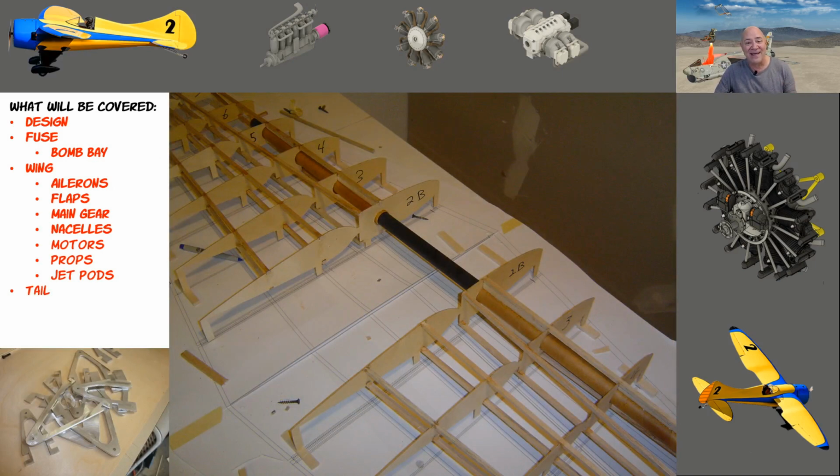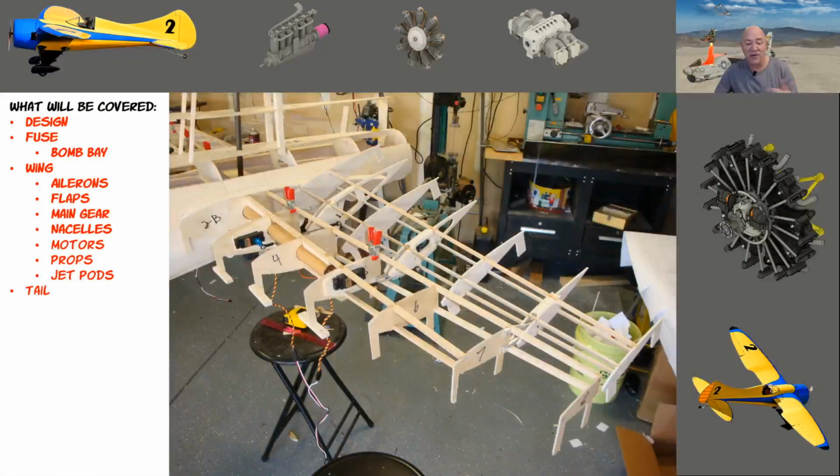And now when we talk about the tail, the most interesting thing about the tail on this airplane is I had to build it as light as I possibly could because I already knew I was going to add a lot of ballast in the nose. So I went back to putting a carbon fiber tube in there to make sure it wouldn't fall off. But the elevators on this are like 20 or 30% bigger than the actual horizontal stab.